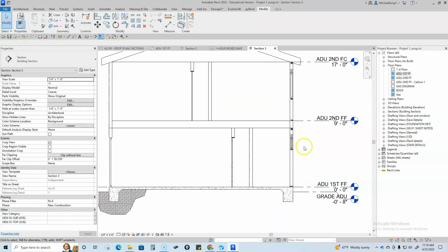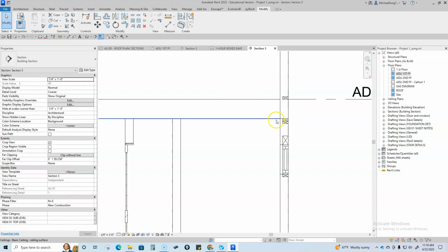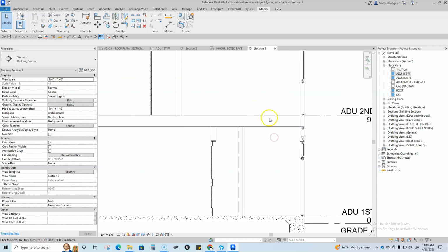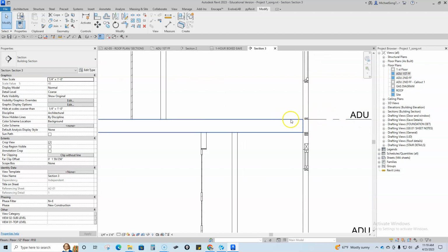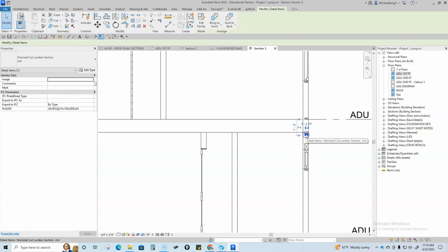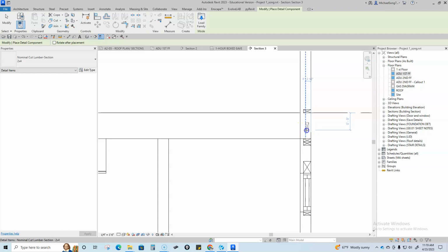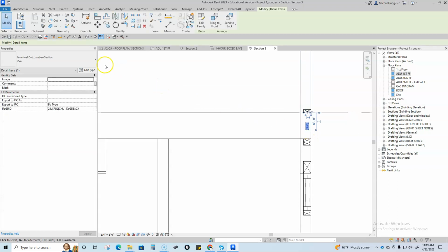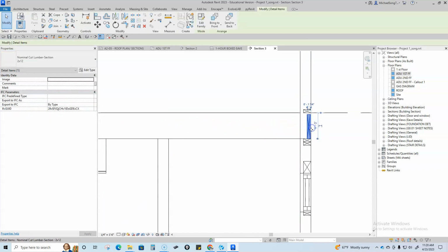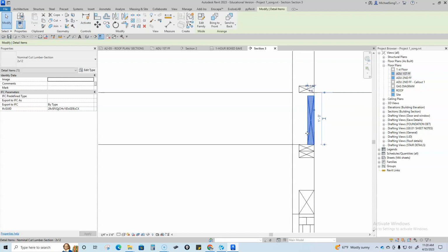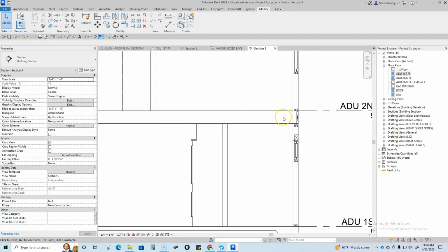All right, so we have the wall assembly. These are the floor joists. So what's really important is the finished floor height. That's where they're going to put the plywood or the floor joist. So we're going to copy this and we're going to pop this in. But we're going to use a 12-inch. So they usually have a rim joist of some sort, and then the floor joist continues.